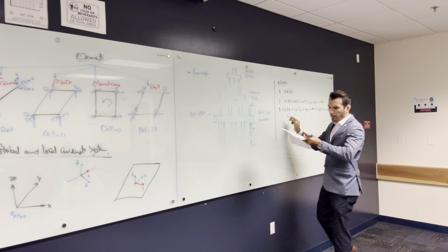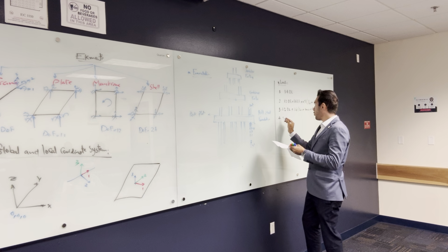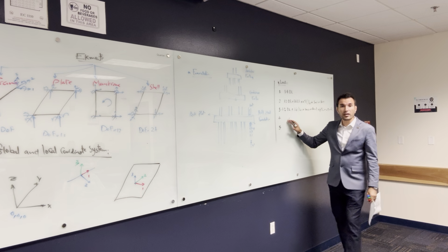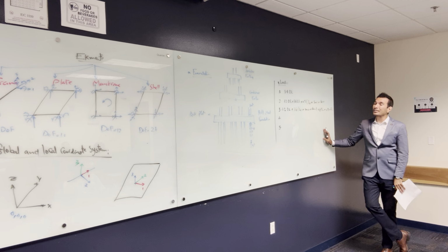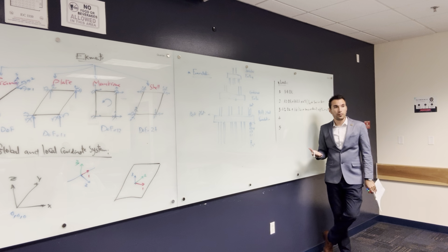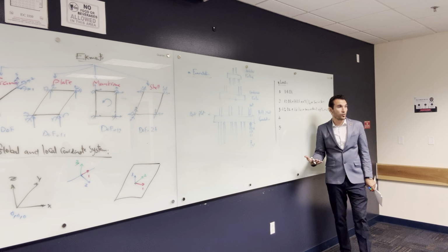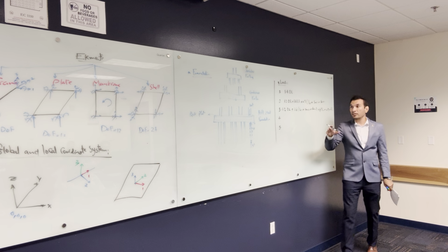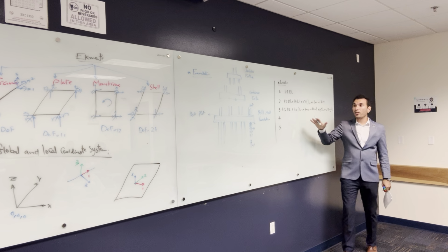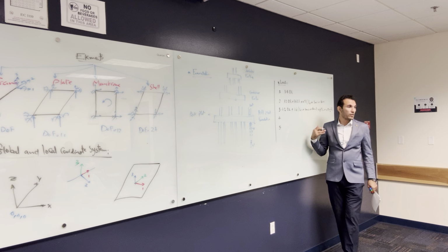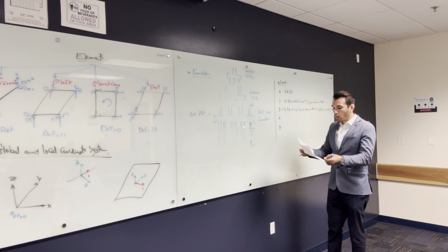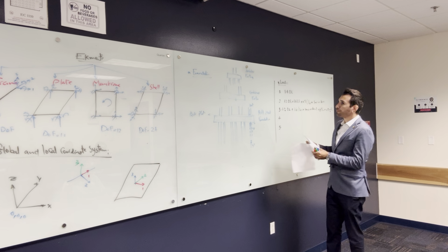Anyway, there are multiple of them and I'm not going to write all of them, say 4, 5. You can check the standards and you will find all of them. In this class I'm going to use only dead and live, just for example. But when you design real structures, and also in tall building design, we're going to design for wind and seismic. In real structures, you have to follow specific load combinations when you design the structure elements. So that's for the loads.